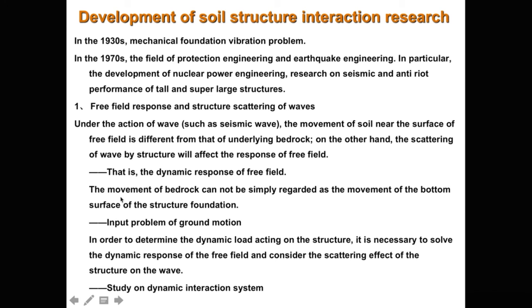And the movement of bedrock cannot be simply regarded as the movement of the bottom surface of the structure foundation. That means the input problem of ground motion. Because the foundation, usually we take it as bedrock, has deformation, not a rigid body. Then it will affect the response of upper structures.